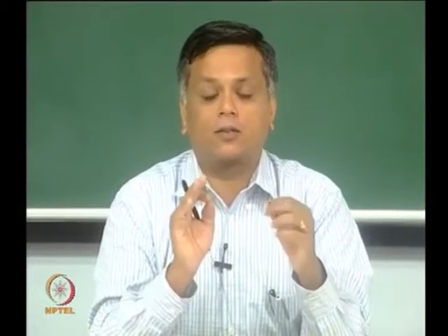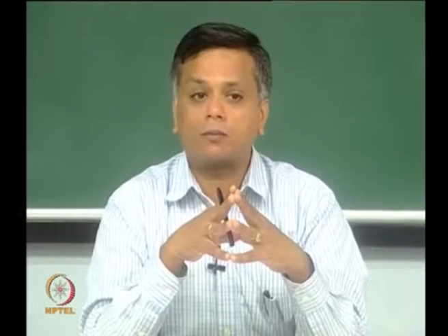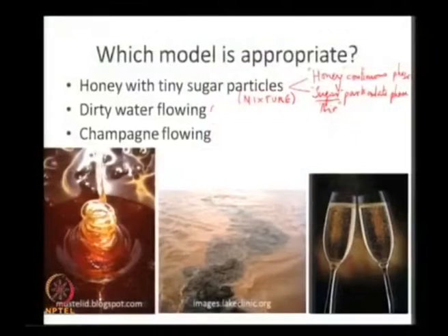When this is the case, when the silt phase tries to do something slightly different from the water phase, your mixture assumption is not completely accurate. Your two phase flow modeling approach is more accurate, because the silt has a mind of its own, has an inertia of its own. Okay. So, this dirty water problem is ripe for two phase flow modeling.